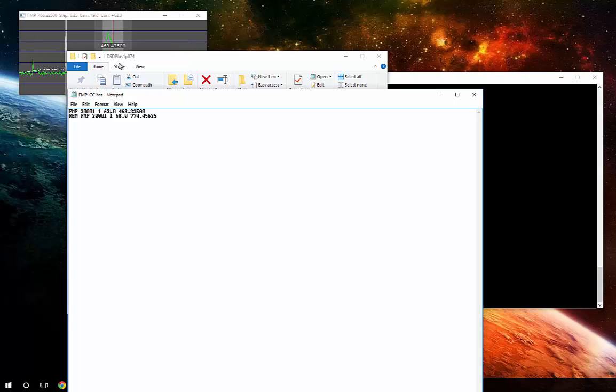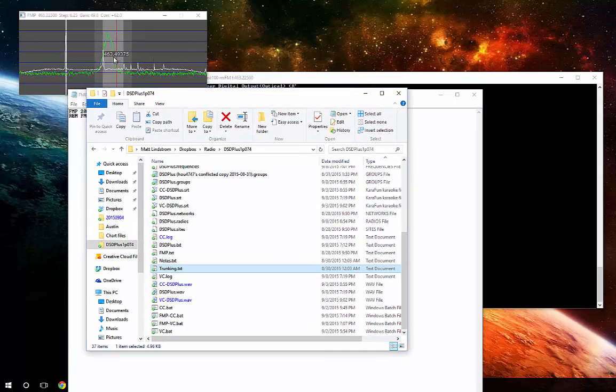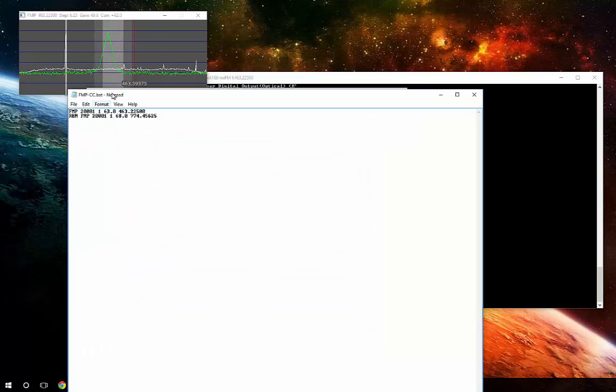And it continues to drift back there. Look at that, look at that chip heat up. So I'm going to put it at what I know it should normally settle around, which is about 67 or 68, just because it will continue to drift as it warms up, which hopefully in a future release they will adopt something that Unitrunker does. Unitrunker actually has an option for drift following, which I believe actually adjusts the PPM fix.